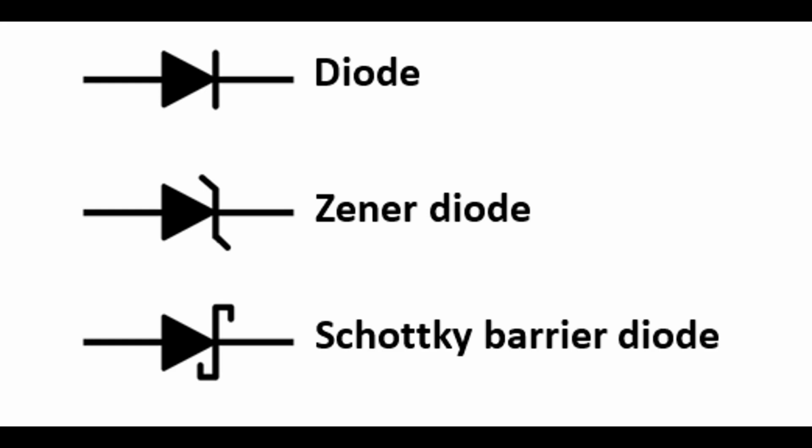In solar cells, this effect occurs when photons, particles of light, strike the surface of the semiconductor material, exciting electrons and creating electron-hole pairs. The semiconductor's built-in electric field then separates these electron-hole pairs, causing electrons to flow in one direction, creating an electric current.